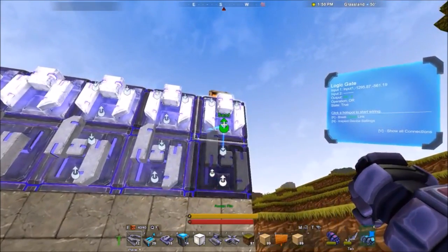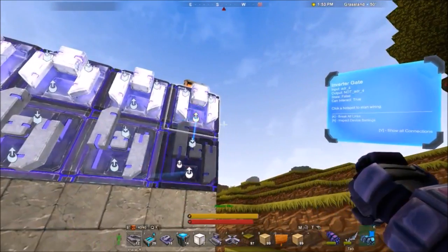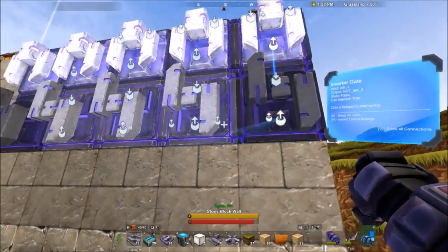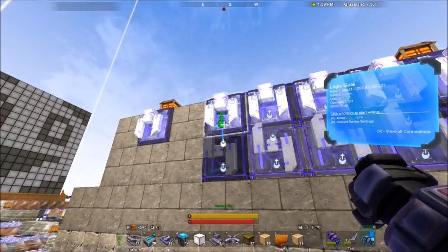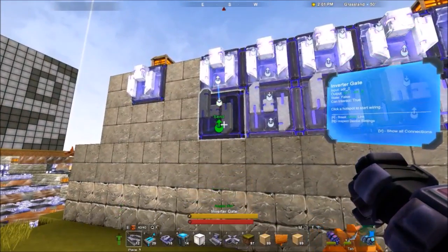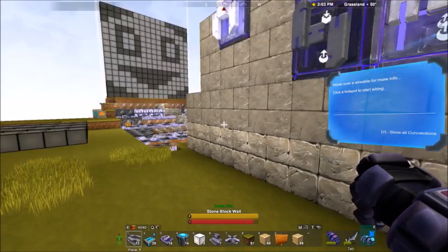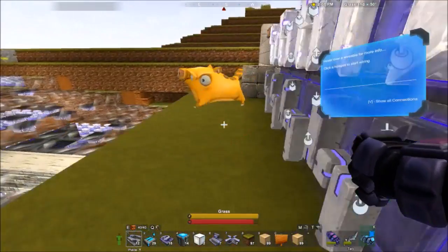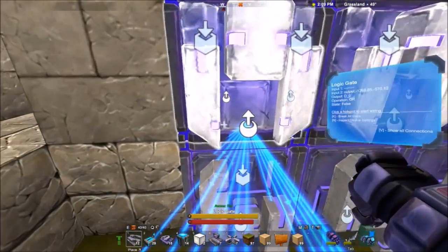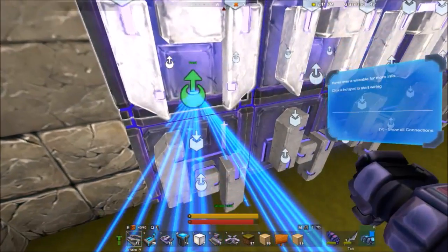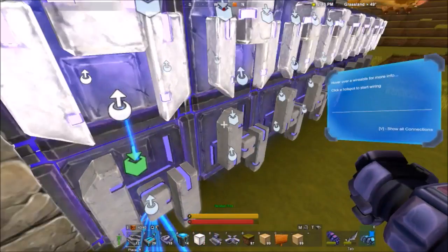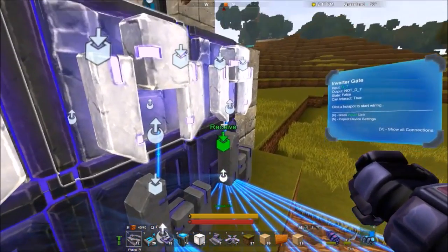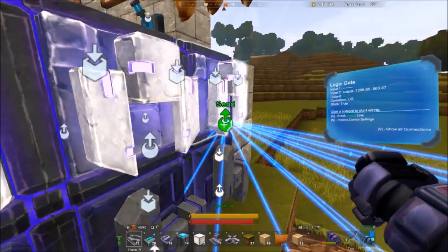First of all, this is gonna be address 4, which is connected to switch 4 for 16, and this sends not address 4. This is using an inverter. The same way, this one is address 0, and it sends not address 0. I'm gonna show you how it works on the decoder, and the same thing we're doing with the data. This is gonna be data 0, and it sends not data 0. This is needed for the D latches, and this is the same out to data 7 and not data 7.